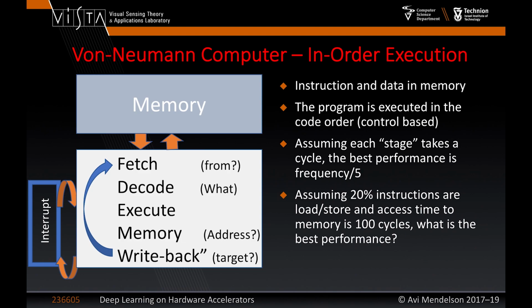So when we fetch something, there is some side effect that automatically this register goes to the next instruction. So next time that we reach the fetch, if nothing happened, if we didn't change the address, we will fetch from the next instruction. This is why we are actually going instruction by instruction. So we fetch and then we decode. Now after we fetch, we have it in the instruction buffer, so now we can decode it. It tells us what we should do, and we execute.